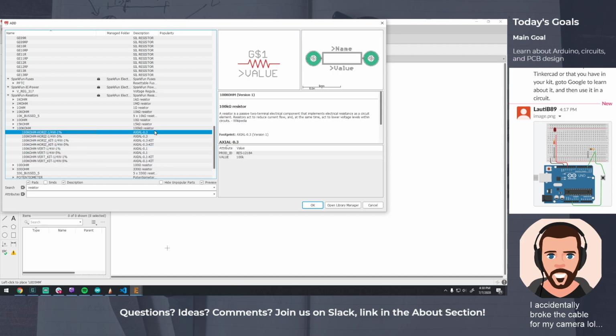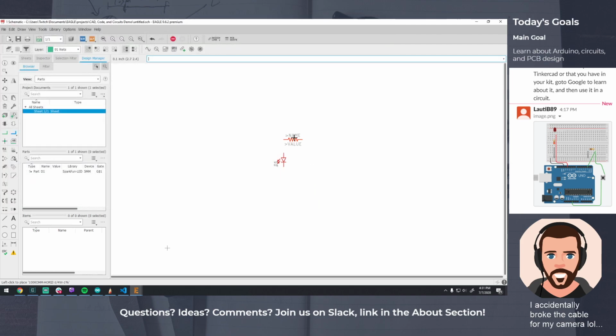Okay, so it looks like this actually has the footprint of what we want. You can see the symbol here that we recall from the previous bit. We can get little descriptions here of what this is. So it is a resistor, commonly used for quarter watt through-hole resistors, 0.3 inches between the holes. So that sounds good. So we'll drag that in.